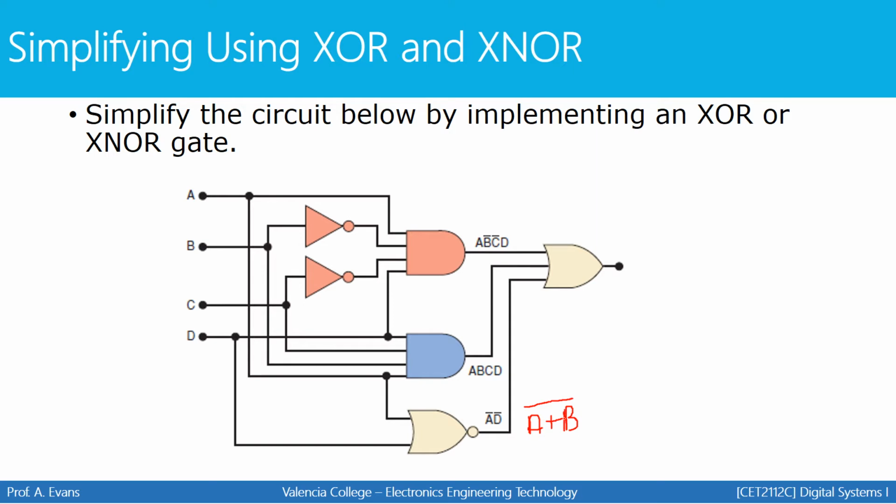Oh, I'm sorry, that should be a D. So if you're wondering why this particular label doesn't say A or D as a group inverted, that's because it's just written after De Morgan's has been applied. Break the bar, change the sign, and you'll end up with this expression here. So you could write this either way, but eventually you're going to have to apply De Morgan's for simplification purposes. So this is just cutting that one step out.